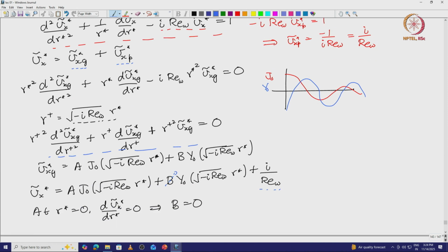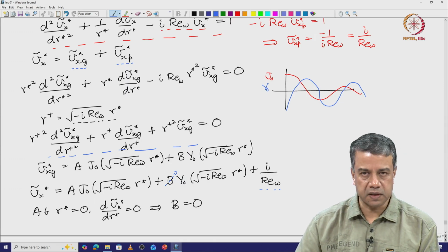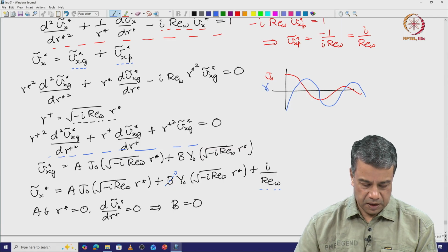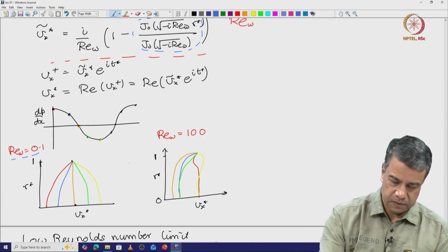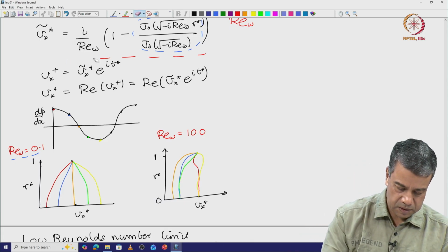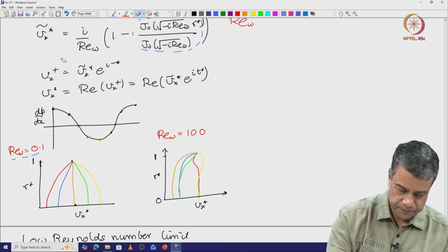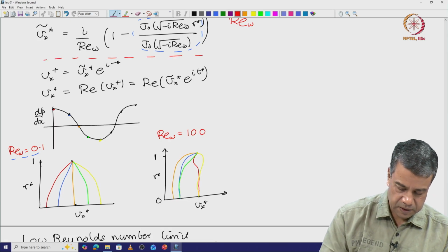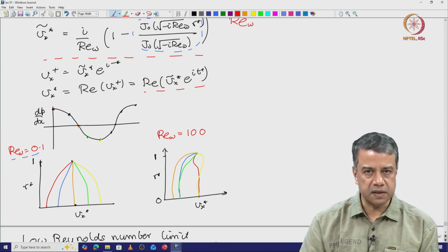So, we had got an analytical solution for this in terms of Bessel functions, if you recall, in the class before the previous one, that satisfied both the boundary conditions. And for this I had also plotted the velocity field for you. So, the solution was this one. I have to take the real part of Vx tilde e power i t, where Vx tilde is this, and then I get the solution for the velocity field.